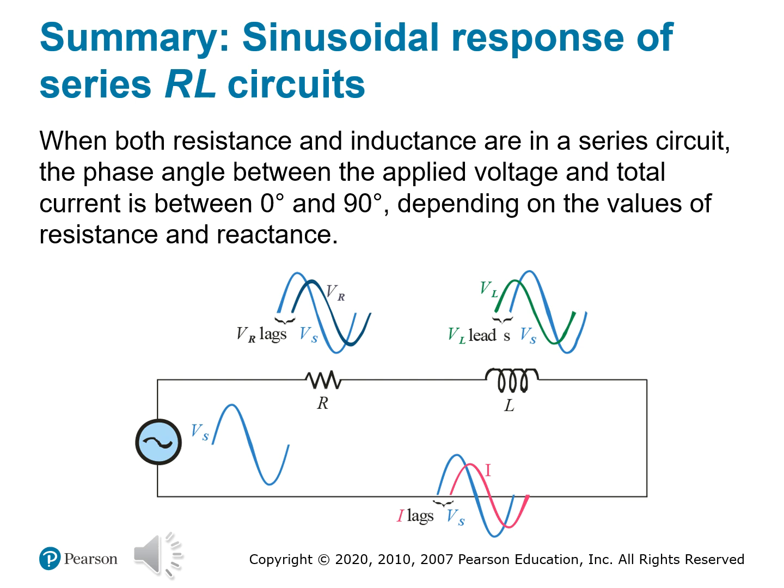When you apply a sine wave to a series RL circuit, here's what happens. Voltage, denoted here by V sub S, is the source signal. Current, denoted by I, flows through both R and L, but it doesn't align exactly with V sub S, the voltage source. Instead, current lags voltage because of the inductor. The lag is a phase angle somewhere between 0 and 90 degrees. And why not a full 90 degrees like a pure inductor? Because now resistance is in the mix.